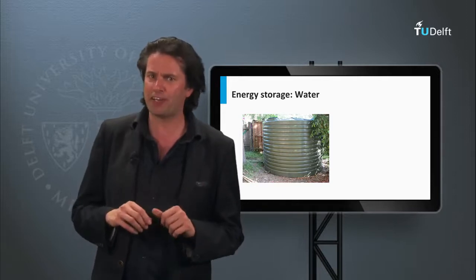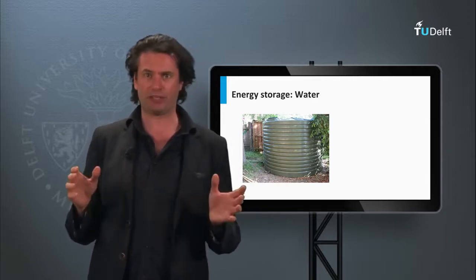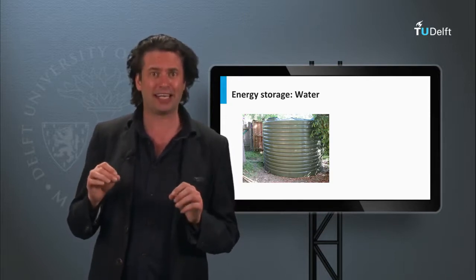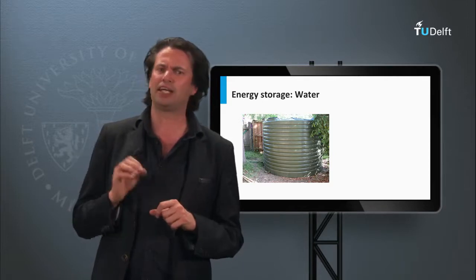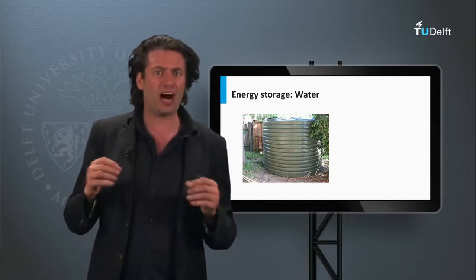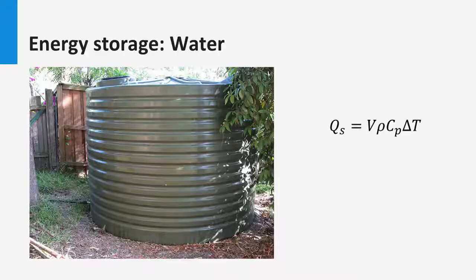Water is the most frequently used storage medium for liquid systems because it's inexpensive, non-toxic, and it has a high storage capacity. In addition, the energy can be transported by the storage water itself without the need for extra heat exchangers. The usual energy stored in a water tank can be calculated with the formula shown, where V is the volume in the tank, ρ is the density of the water in the tank, Cp is the specific heat capacity of the fluid, and ΔT is the temperature range of operation.